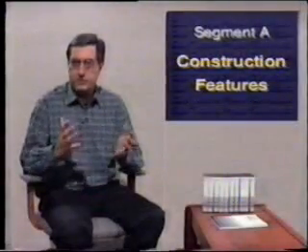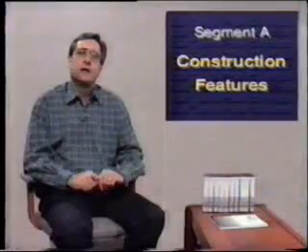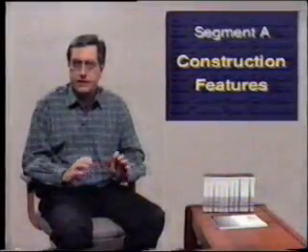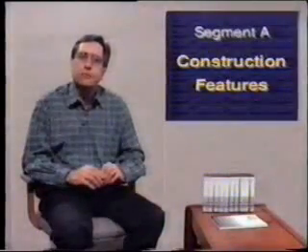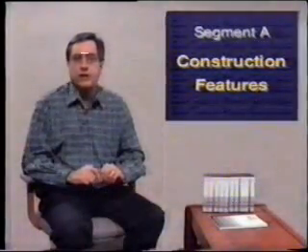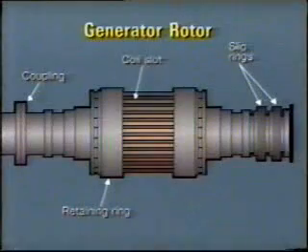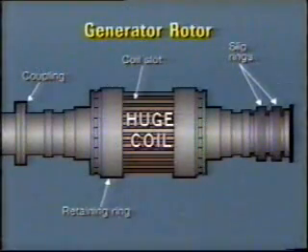So the rotor provides the rotation, but where does the magnetic field come from? Well, I suppose this could be provided by a permanent magnet, but this would provide no means of control, and probably the field would not be strong enough. In actual fact, the magnetic field is created by a rotor winding. Insulated solid copper conductors are embedded in rotor slots, and they are located in such a manner as to form a huge coil which turns with the rotor.